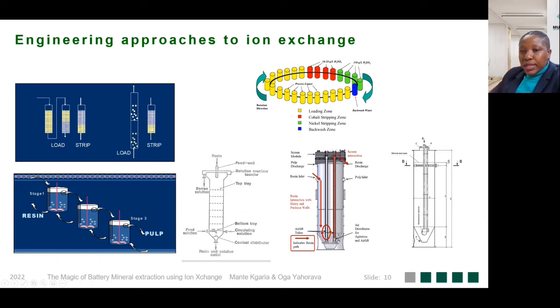Multotec, in collaboration with Clean TeQ, offers moving bed ion exchange systems, which provide added benefit in terms of resin utilization and inventory. They provide an added advantage when it comes to elution, where there is optimized reagent utilization and generation of small volume liquor. Clean ion exchange metal recovery technology provides a continuous countercurrent approach to ion exchange, thereby optimally exploiting ion exchange resin chemistry to deliver richer metal liquors and improved water balance around the circuit.